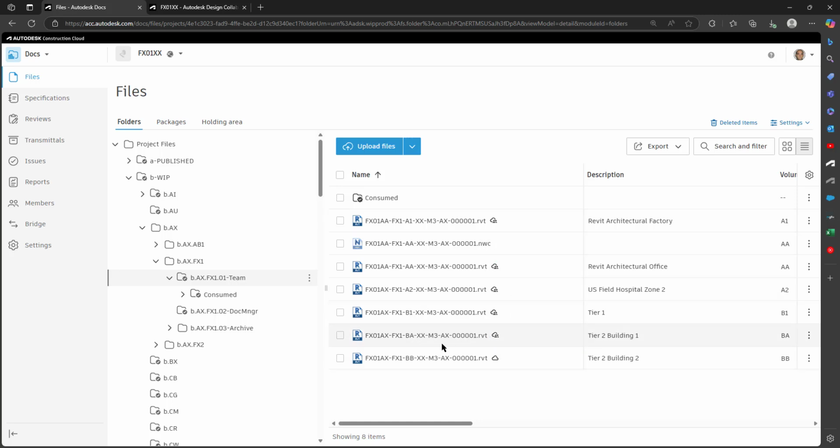And after that, if you want to edit one of those typical designs, then you would have to repurpose that link onto the file within the work in progress folder, alter the work in progress folder second tier, and go through a two-tranche package sharing scenario again. The first tranche, share the second tier models. In the first tier models, change the link paths to the shared folder, and then publish the first tier models after that. I say publish, but of course it is sharing the package. So that's the process. We can perhaps demonstrate that.